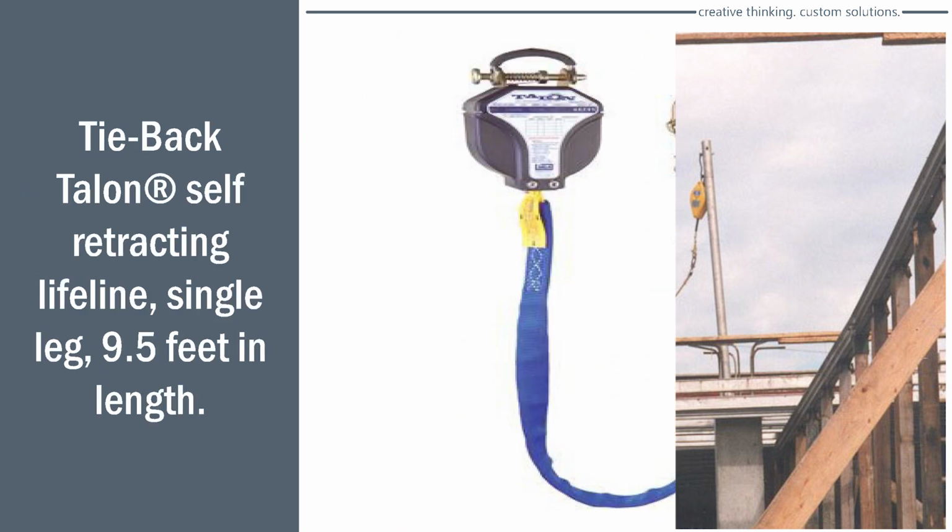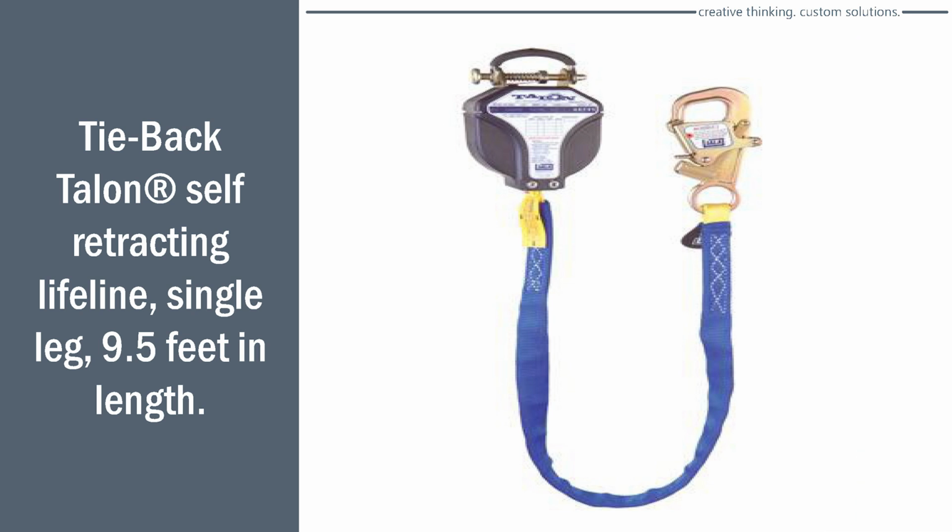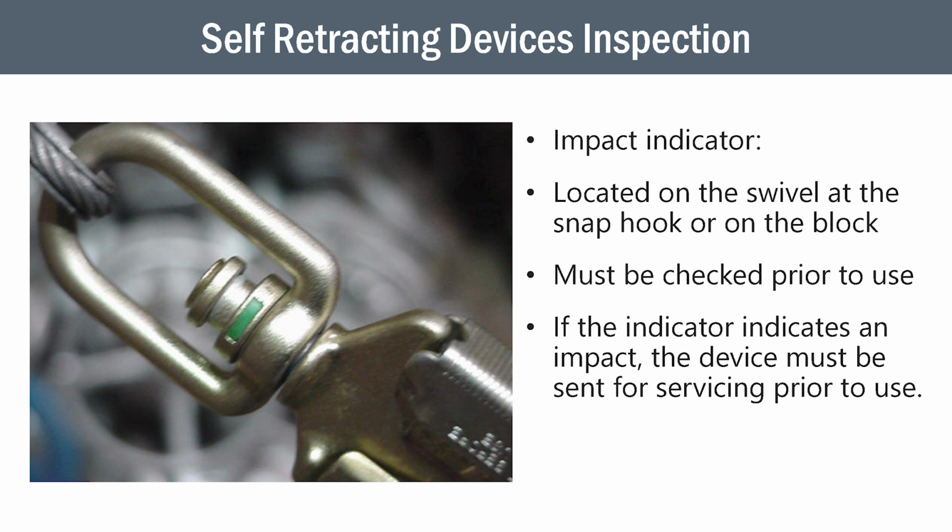All right. Just another picture. I like the way this was set up. You can get these lanyards on these SRLs in different lengths. It's up to you. But when you go to inspect them, one thing I like people to look at is the pin.